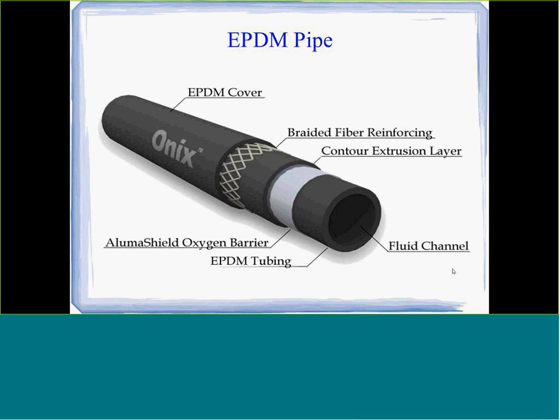The other advantage is if you're doing a large area, a big warehouse or something, and you don't have a pump to pump the concrete in, you can actually back trucks over the Onyx, and it will not crush the pipe. The pipe will flatten out, but as soon as the weight comes off it, it pops back into its original shape, where you can't do that with some of the other pipe.